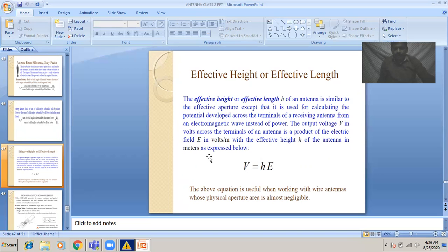That means the transmitting antenna effective length and similarly the receiving antenna effective length are the same. For an antenna acting as a transmitting antenna, and if the same antenna is utilized as a receiving antenna, the effective length is also the same, from the reciprocity theorem.